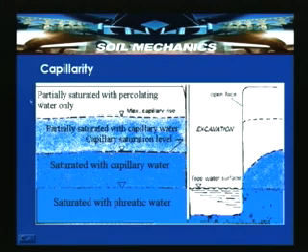Then above that is the percolating water, or whatever we are discussing, which is nothing but contact water. So, here we can see the partially saturated with percolating water zone, that is the contact water zone, and this is the partially saturated capillary zone, and this is the completely saturated capillary zone, and this is our conventional saturated zone below the groundwater table.